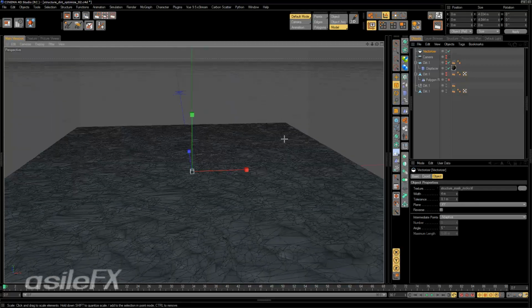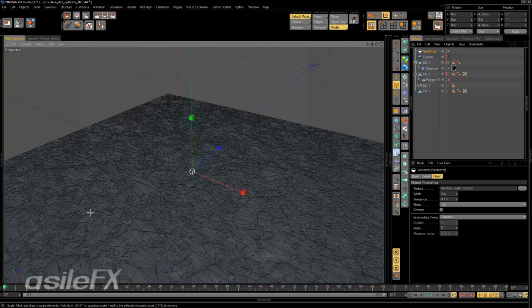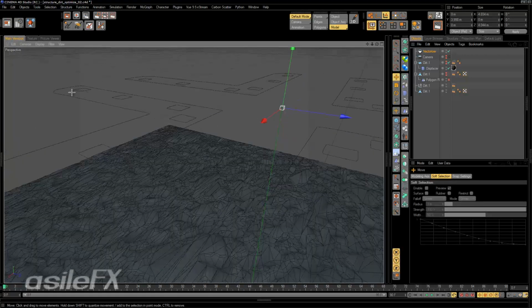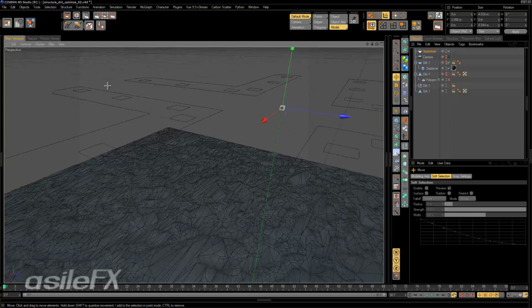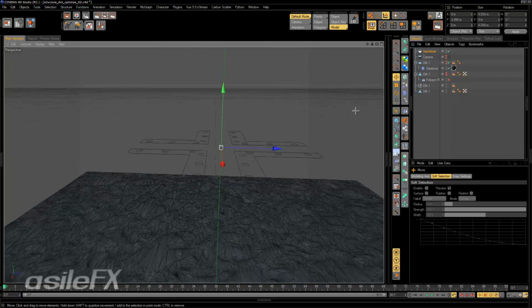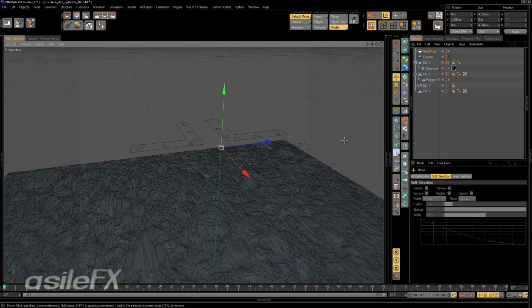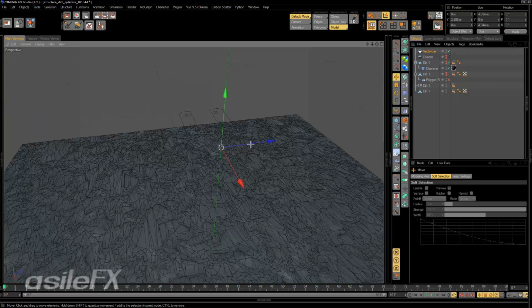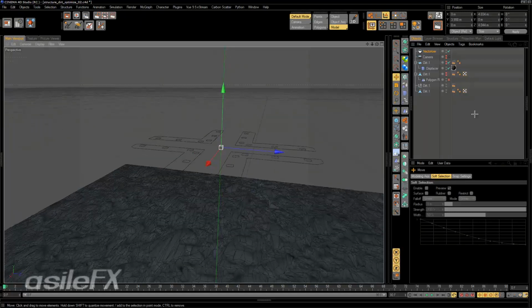But basically, once I bake this object, the scale of it is going to be equal to the ends of the spline that's created rather than the original source image scale. So I could go into the image itself, modify it, and add just a few pixels on the corners to adjust that size so that I can match it to the plane.